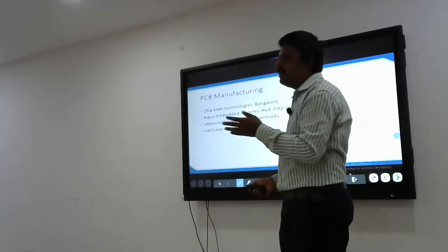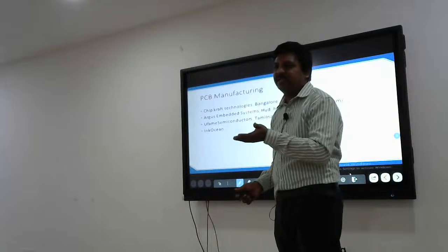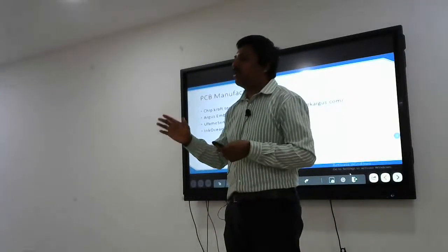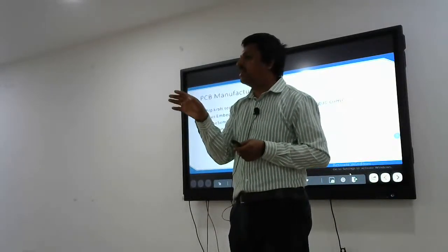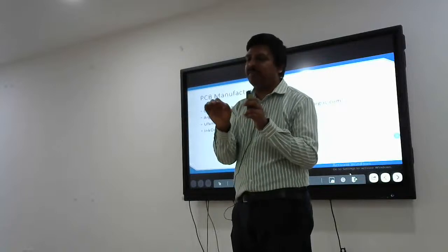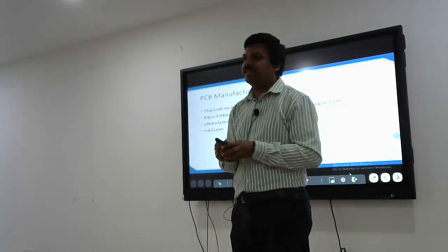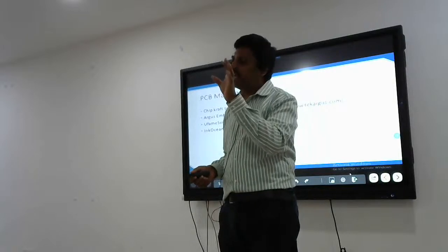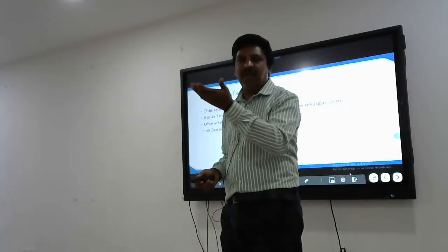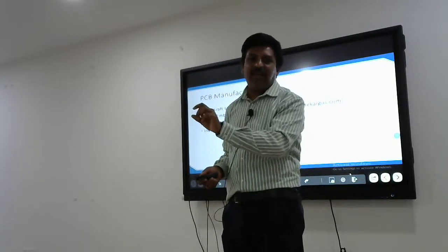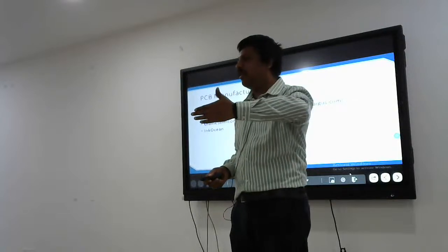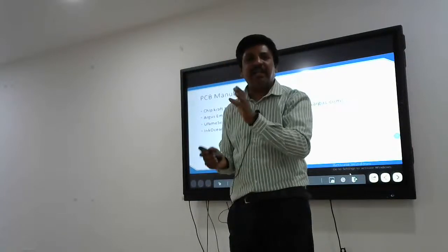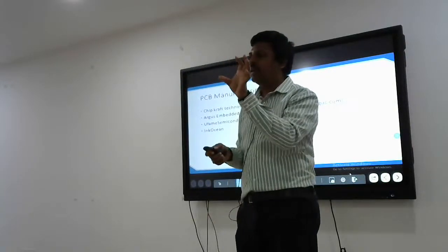Some PCB manufacturers, what I suggest is, if somebody is starting in hardware, then you can go to the Texas Instruments design files. You just type TI design files. If you want to do an inverter, you just type TI design files inverter. Then some design files will appear. You just open them and try to understand what they say.